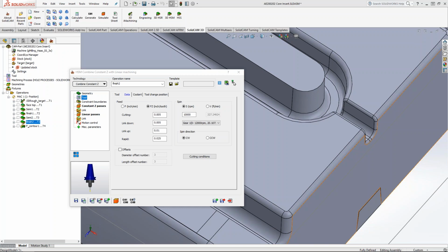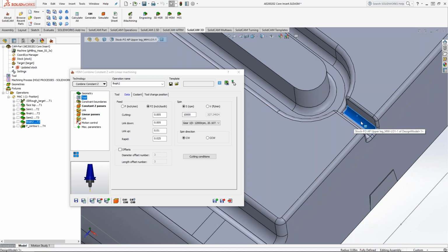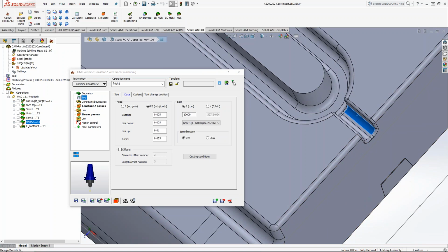And again, this is a perfect example. This little area over here, especially if it's a lot smaller, you've got to use a smaller ball mill. With that machine I had, that VM3 with the 12,000 RPM spindle, I've used 12 thousandths diameter ball nose that were, I think, like a 1/4 inch cut. It might have been 20 times diameter as far as reach goes. So I've had to cut 15 thousandths deep, 15 thousandths wide ribs, 3/16 deep with that machine.